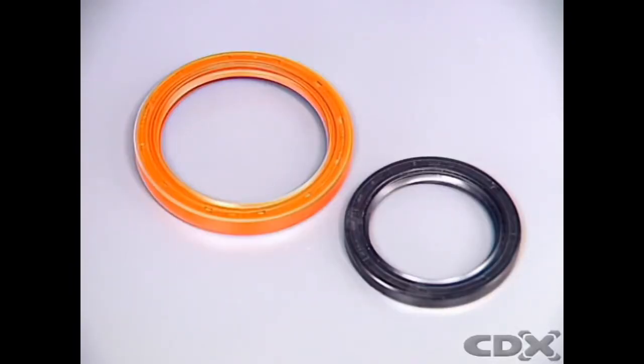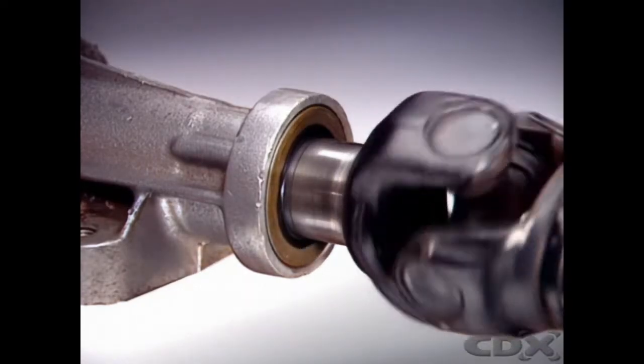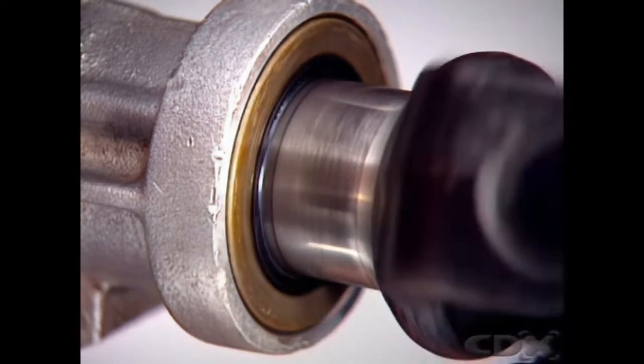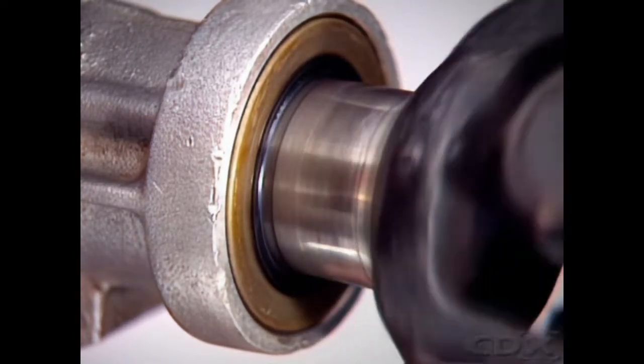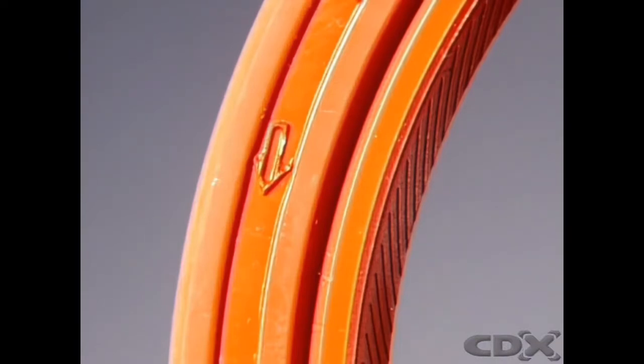They can also be hydrodynamic type seals, with helical flutes molded into the sealing lip. The flutes create a pumping action as the shaft rotates, so any oil at the sealing edge is drawn back inside the casing. Since the flutes are molded in one direction during manufacture, care must be taken to ensure they are correctly applied, considering the direction of shaft rotation.